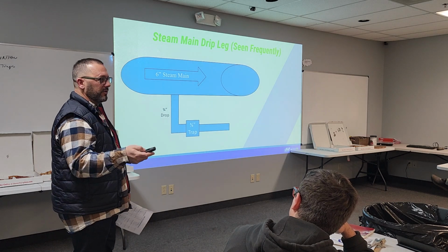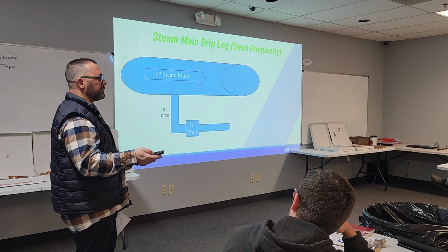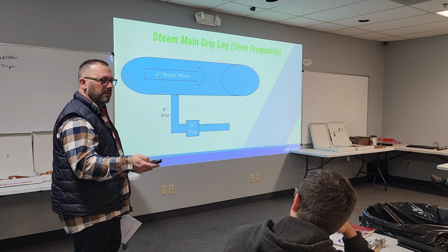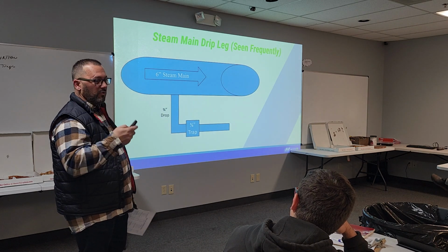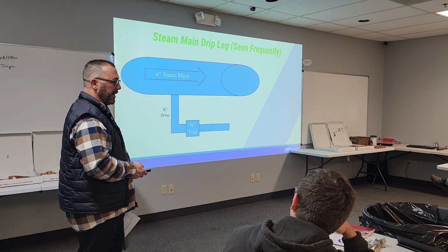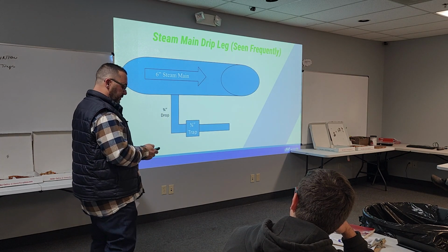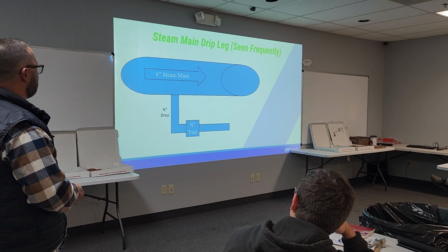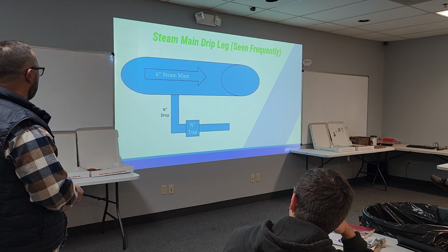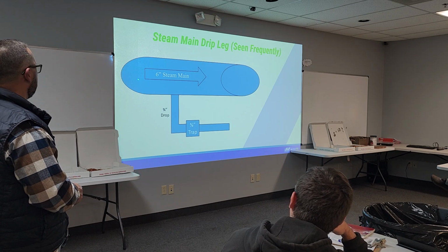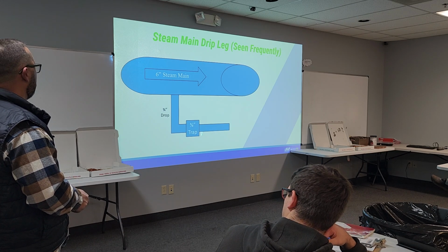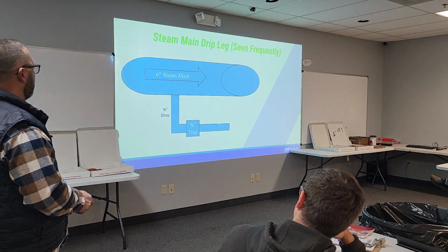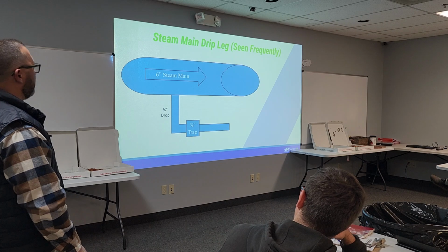In these steam mains, there's really not that much going on. You might need a trap that's going to pass 200, maybe 300 pounds per hour, which the TD traps are well over, the capacity is more than good for that. But I told you, you need a 1/2 inch or a 3/4 inch trap. So you got a 6-inch steam main, and then you bought a 3/4 inch trap, and you took the 3/4 inch drop and a 3/4 inch pipe.